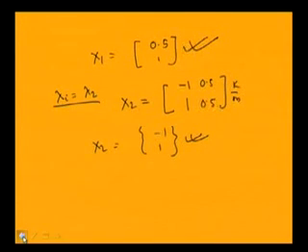So, in today's class we have studied finding the stiffness matrix of a multi-degree of freedom system. From the definition of the stiffness matrix, each element, the k i j element, can be defined as the force required at i to have unit displacement at j and displacement at other places equal to 0.